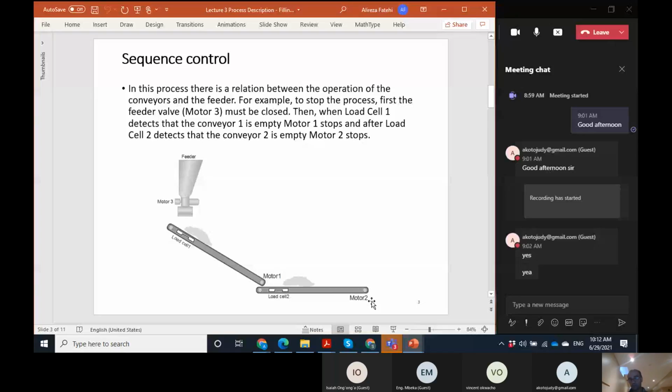You know that from the electric point of view, the motors at the beginning when they are stopped, because of the inertia, when we start the motor, they need more current. And if there is material on the conveyor, because this is heavier, in that case we need higher current, and maybe the motor cannot, or there might be some damage on the motor, or maybe the lifetime of the motor reduces significantly. Maybe the motor was going to work for, I don't know, 10 years, but after 1 year you see that the motor is gone. It's because of that high power, high current at the start.